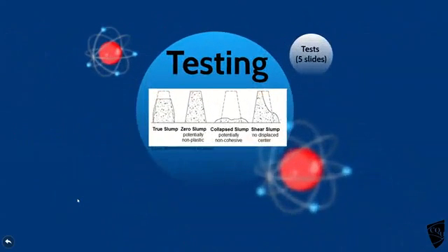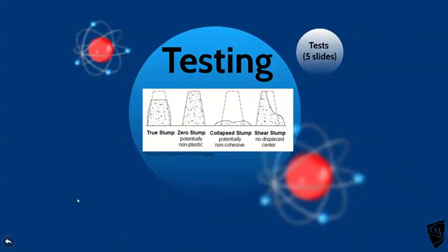The slump test. When you design your concrete mixture, part of the design will tell you you want a true slump. And there are some slides on how to do it up here. The true slump here. Okay, you put it into this conical mould, pop it down on the ground, and as you pull the mould off, it should sit like that.